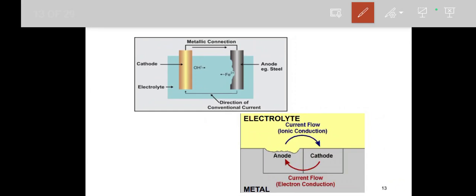You might also have seen another concept called coating, gold coating, silver coating. Suppose you want to coat a steel material with silver or gold: that silver or gold will be placed in the electrolyte medium, and the steel will be placed in the same electrolyte medium, and we have to make the gold or silver the anode, with the positive charge connected to that and the negative charge connected to the steel plate where the silver or gold is to be deposited.